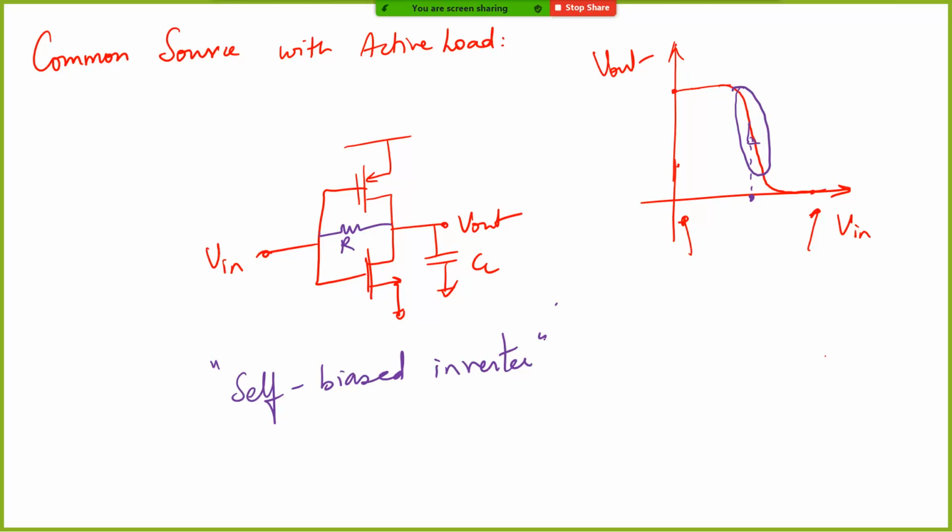In such cases, when the signals are flowing at the receiver end, the signals are not very good square waves. They become more like sine waves because of the bandwidth limitation of your PCB channel between your DDR RAM and your processor. The same thing happens in network backplanes and so on. That's a whole area of work. In fact, the MTech students will have a course next semester, mixed signal VLSI, where half the course we look at high-speed I/O interconnects. So in situations like this, under certain circumstances, you use circuits like this.